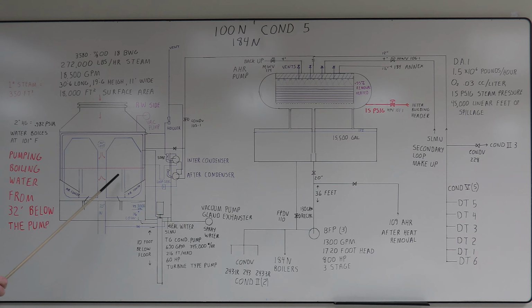A lot of surface condensers, it seems like they build air up in the middle of them. So they had like an air lane in the middle. They went down through an air cooler section. Then any non-condensable gases would go back.